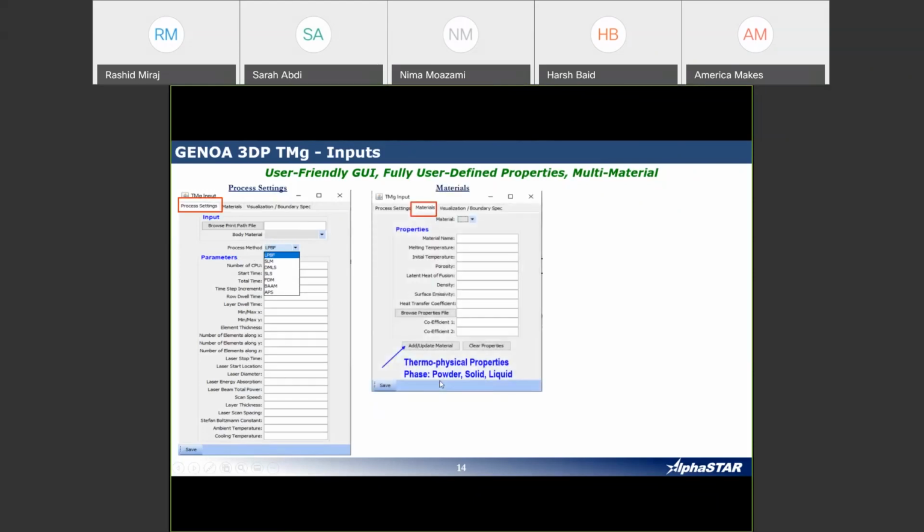Now, the next input would be the thermomechanical, the advanced physics properties. Nothing outrageously on the scientific curve, standard stuff you should have: heat transfer coefficients, densities, initial densities, latent heat of fusion, those kinds of things. And any material that you might have in a database, any preselected materials, will pop up. Again, a tool, not just asking you to input, but an interactive tool that has access to data that you used before, data that you're currently working on.